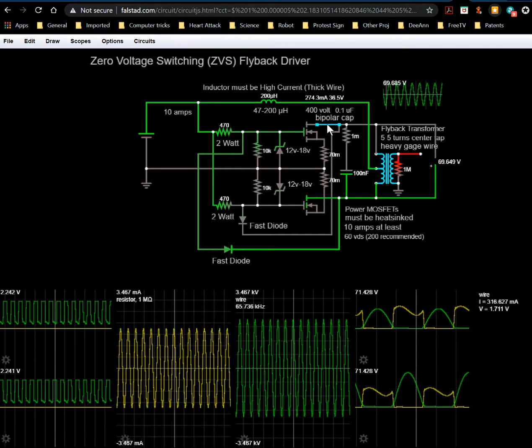Incidentally, the fact of the matter is that this voltage here is on top of this ground voltage. So that's where it's 71 volts, right? Because otherwise this thing's not connected to ground. I mean, this tank circuit you can consider independent. That's why I was talking earlier about how you could have this tank circuit just with a switch attached to it, and you could just disconnect the switch and it'll still oscillate. It doesn't have to have anything to do with ground. You can completely take the battery out; it'll still oscillate.